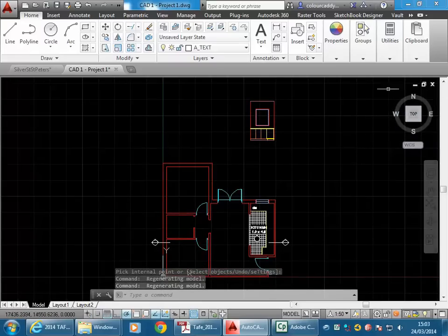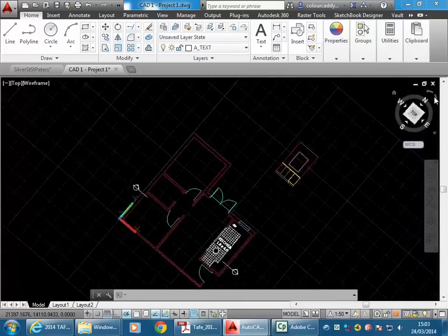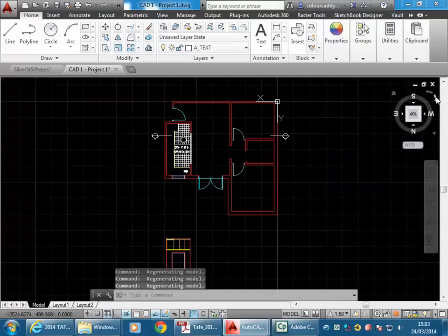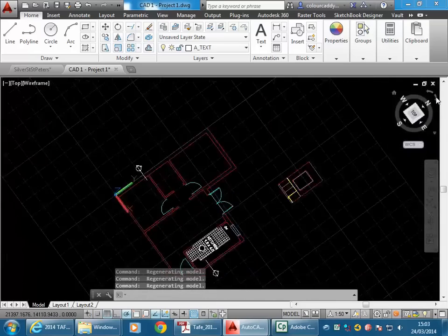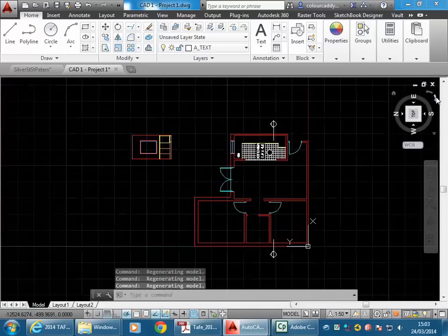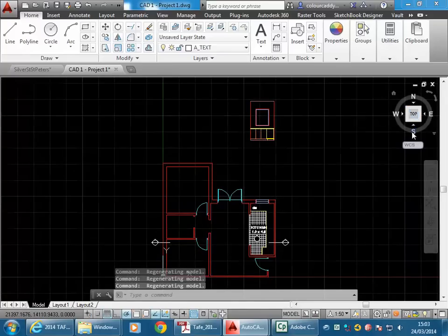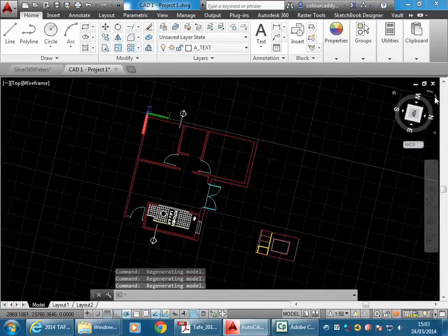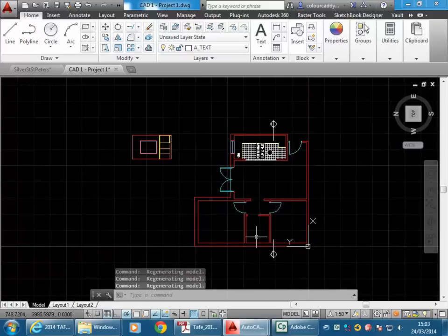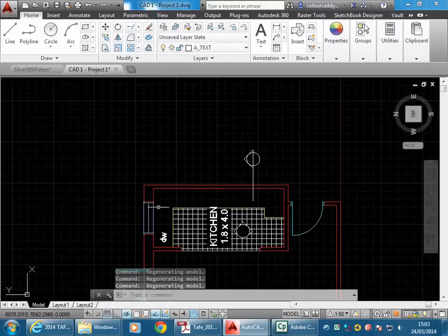And then to control these view directions, you can use the compass points, but for now we don't even need to go to those. We can just rotate the view using the arrows in the very corner, and that'll just flip it around, viewed from above, which is exactly what we want here. So you can see that, again, using the top view always. So if you're not sure, make sure it is on top. Really important. And then again, you can simply rotate around until you get the angle that you want. So here now I can project up to draw this side of the kitchen.